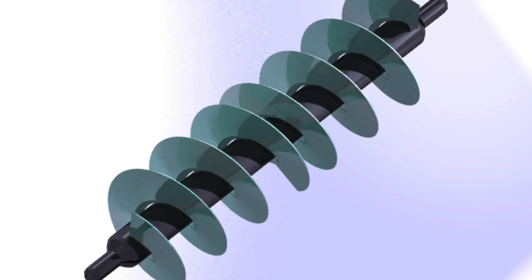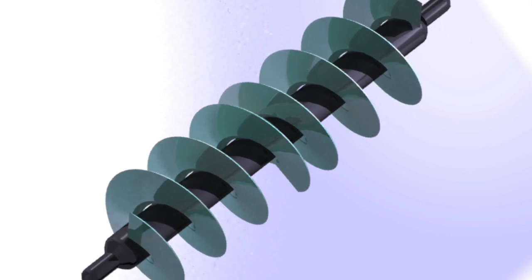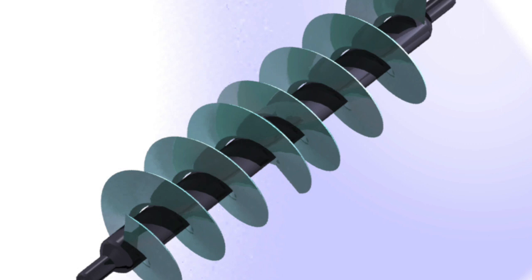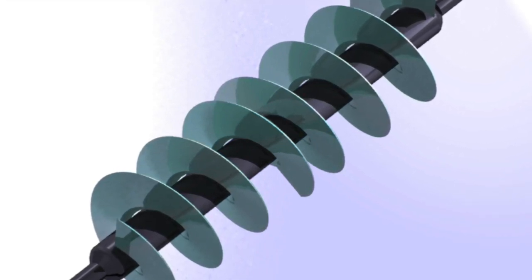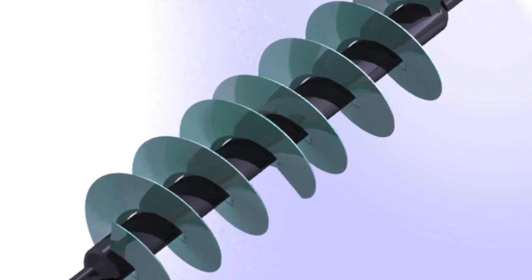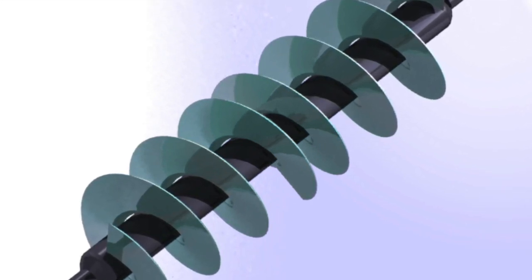The beginning of our process was the design proposal stage. During this stage, we researched different concepts that we could incorporate into our heat exchanger in order to increase overall effectiveness. Some of these ideas were later improved upon while others were rejected. An example of an idea that was improved upon was the Archimedes screw. The concept of the Archimedes screw was to create a vortex in the drain pipe, which would increase effectiveness of the heat exchanger. However, we realized the concept would not work due to destroying the water film. This idea was later improved upon into a spring. The spring can induce turbulence in the drain pipe while keeping the water film intact.